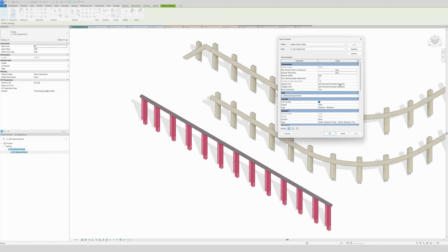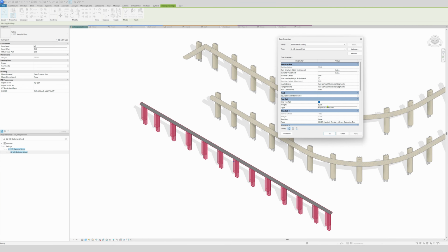So now the next thing that we're going to do is the baluster. So I will use a baluster. Why I don't choose this one? You can only change the height. So we're gonna change to 50 and the height changes. You can't give it an offset. So I won't use those rail.